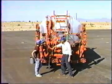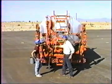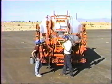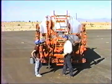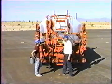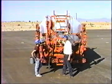If you try to run the pump faster than 300 gallons a minute, all you'll do is cause the pump to cavitate. That is, it will create gaps in the stream of oil coming in, called cavitation, and that actually slows down the pumping process. As you speed this pump up, the pumping efficiency goes up to a point, and that's as fast as it'll come through this hose, and then it goes right down fast.